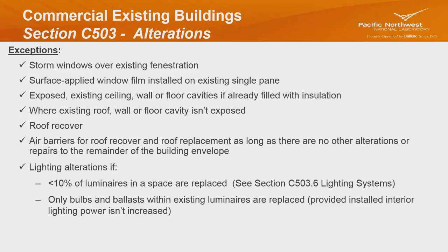In ASHRAE 90.1 2013, the threshold is 10%. COMcheck, the threshold is 10%. So I just want to point out that that is the value that is used. If you're over 10%, then the whole lighting of that space needs to be brought up to code.